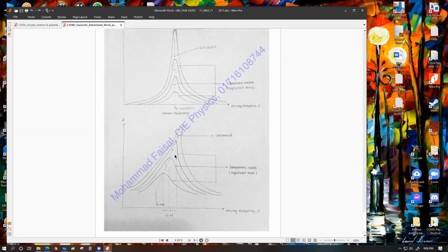What you can see over here, and this is very important, is that as we add bigger and bigger amounts of damping to the system, all of the new curves are lower, below the upper curve. So you are never going to have these lines crossing each other, because having a damping system essentially means you are extracting energy out of the system at a much higher rate, which means you are going to keep on losing energy more rapidly.